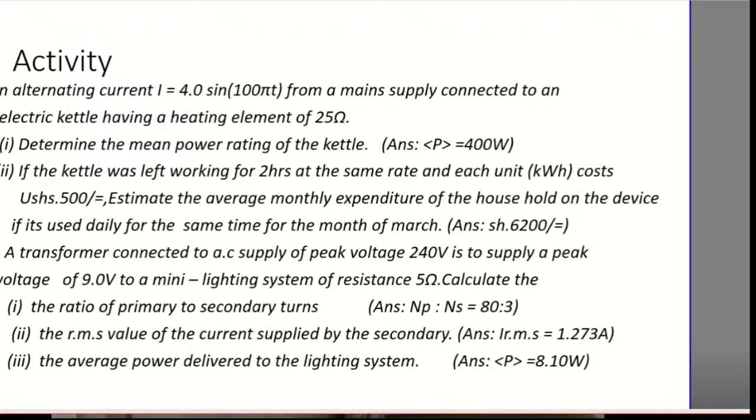So ordinary instruments like an ammeter or voltmeter cannot measure alternating current because the current keeps on changing. And those instruments use torque on a rectangular coil. So that means it will move the coil clockwise and anti-clockwise at the frequency of the alternating current, so the pointer will end up deflecting along the same position.